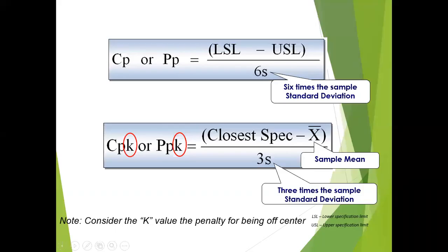Okay. Now we're clear with the shape of the data, the distribution of the data. Now we are going to assess the current process capability in terms of statistics. We already know from a practical point of view where we are performing, because we have the lower specification limit and upper specification limit, and we know the average and we know the standard deviation. We know at what percentage we are performing. Right now, I want to convert that into a measure statistically.